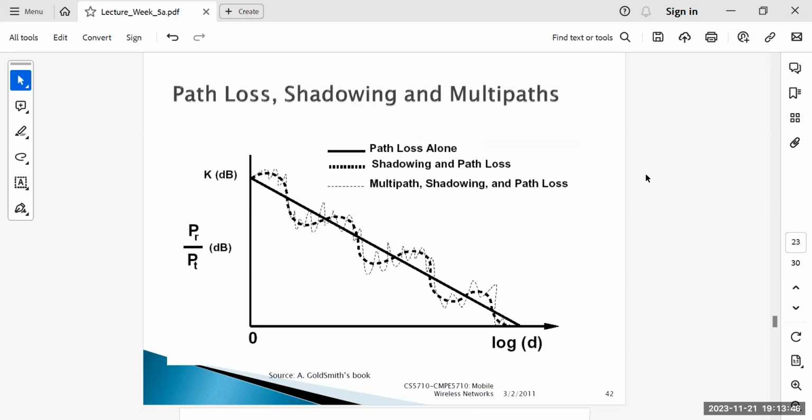A very important graph that you see on your screens is basically showing you the relationship between the received power, or here, that is not the power, this is the dB, this is the ratio of received power to the transmitted power. So when I say this is also showing us the power, obviously we have a power in this, so from that we can say that since the power of the receiver is in the numerator, as this graph goes down, it means the received power is also going down, right? So in that case, you can say that this is also showing us the power, but overall, this is a graph of the ratio of powers, and therefore it is in dB.